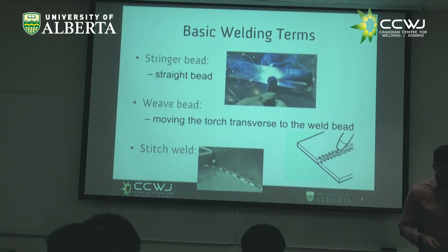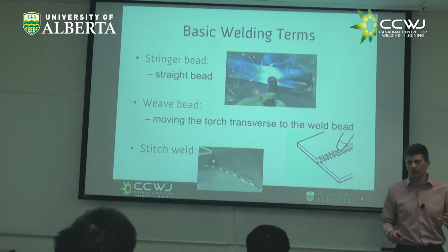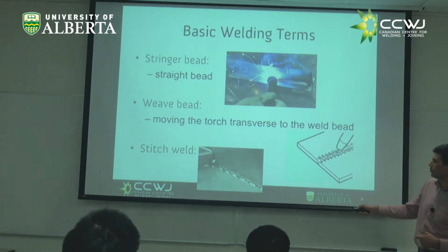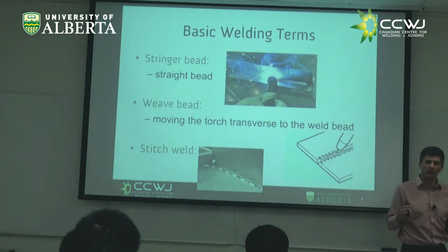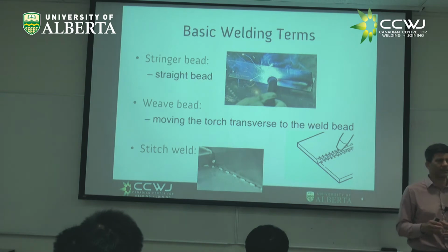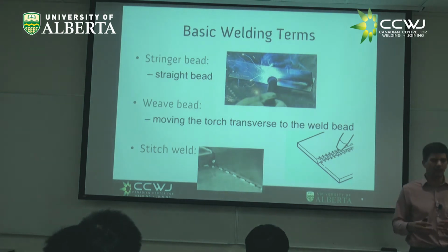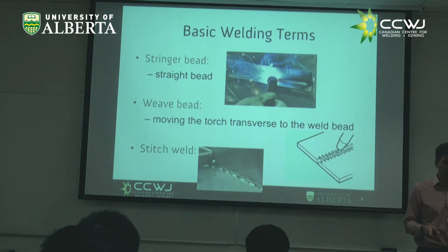But if you do a calculation that tells you your weld should be 1 millimeter, no, you're going to make welds that are at least 3 millimeters. Now, that would be over welding, that would be overheating things, putting too many residual stresses. So in those cases, you would do a stitch weld, right? And that way, you reduce the residual stresses, and you reduce the amount of metal you put, the distortions, you reduce your cost, and you accelerate your time. So all these things, right? Just a word. We're going to be seeing this again and again and again.